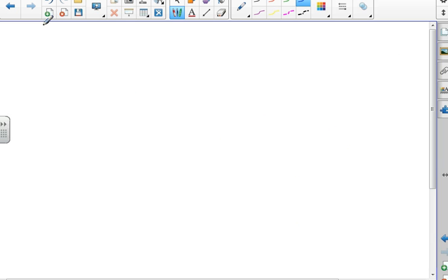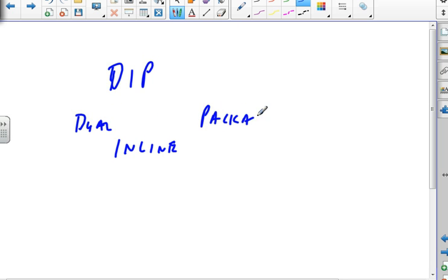All right, on the top of page 42 are dip switches. 102, actually. And a dip switch is a dual inline package, right? So it's many switches hooked in the same hunk of plastic. Used for control purposes, they're not going to be used for sending power through. So it'd be good for 5 volts. If I'm going to send 120 volts through them, I'm going to have my head examined.